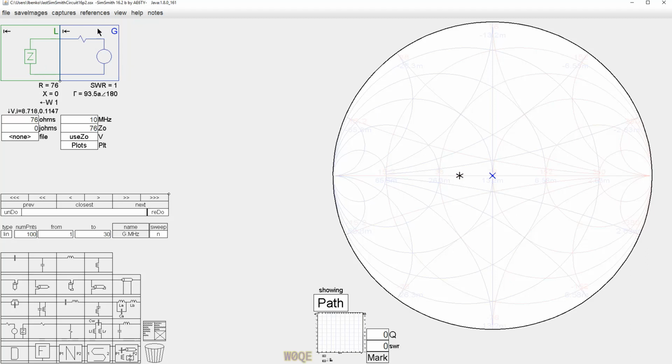You can think of it as being a generator that produces twice the voltage as is necessary when the load's correct, in series with a resistor that matches the load, which is why this symbol is shown this way. This is exactly how every quality signal generator made today works. Although the impedance does not have to be 50 ohms, a lot of times in audio range we use 600 ohms or we use different numbers. I think there are 75 ohm generators out there still too. But this is how a signal generator works.